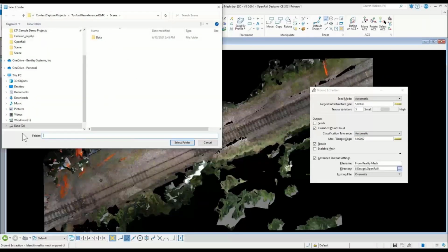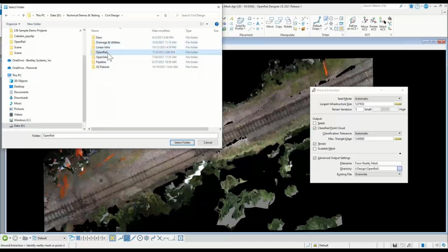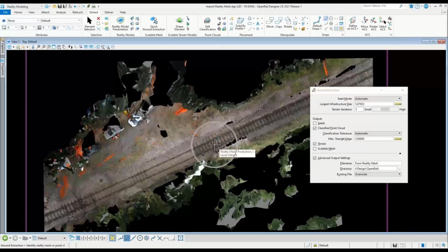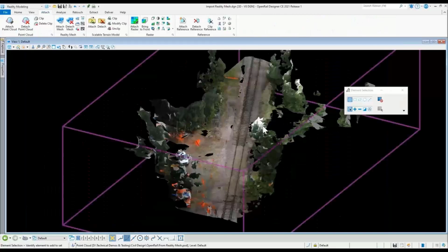Okay, so all you need to do is make sure everything is geo-coordinated. When I say geo-coordinated, everything is in the right position or assigned with the correct coordinate system. Then you just need to input in the GUI all the necessary information for the processing to take place.